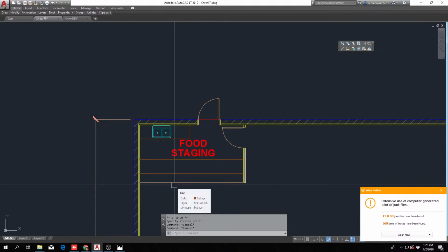Then first of all, whoever is laying out the block has to cut a block, not to the middle of the block, which is the normal thing to do. Cut the block right in the middle. The block measures 8 inches by 16 inches, so they can cut a block at 8 inches, and that's perfect.